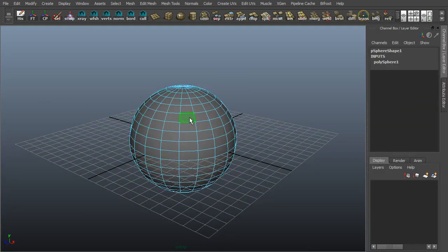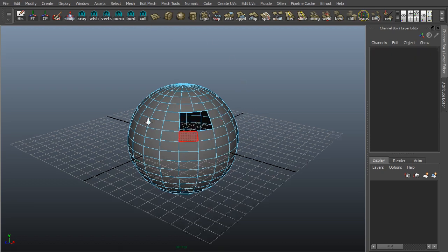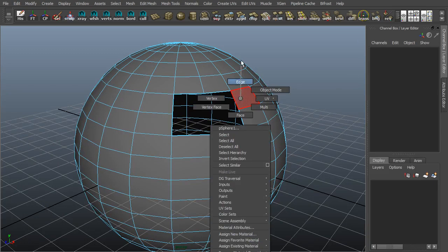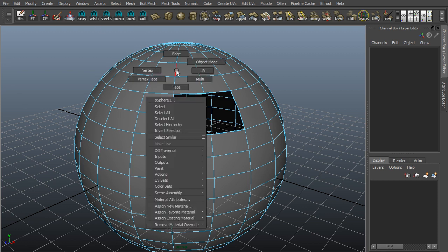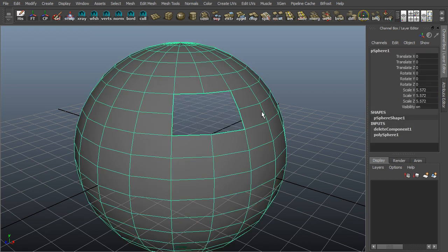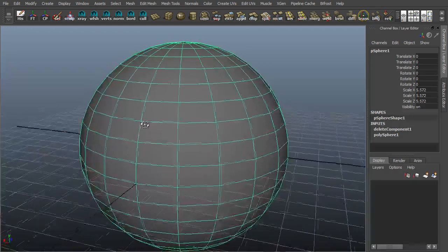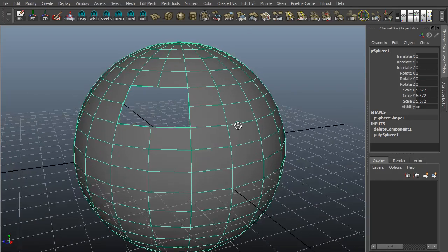And let me delete a couple faces here. This next one right here will show border edges. So you can see that these edges are a little bit thicker than the rest of them. So it's showing that border right there. And then last right here is cull back faces. So if I grab this object and cull back faces, any of the faces where the normal is facing away from the camera, it's not going to display those. They're still there. You can see those were right there. We just don't see them in here.